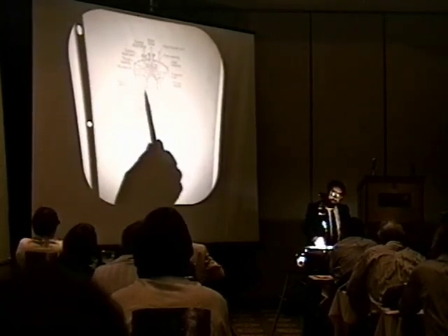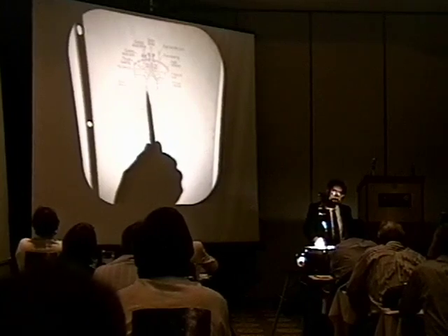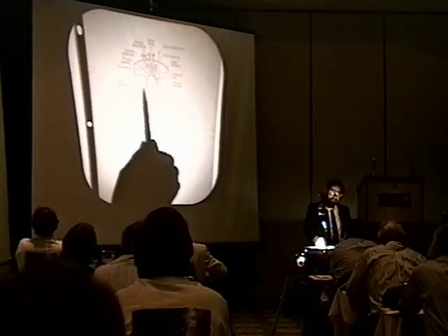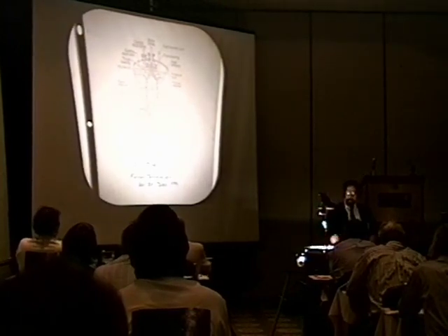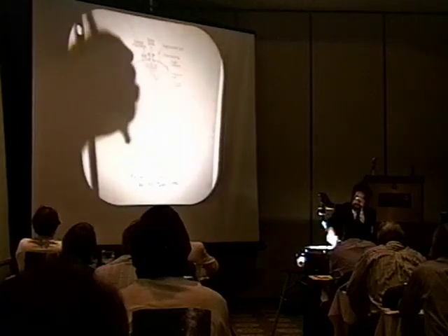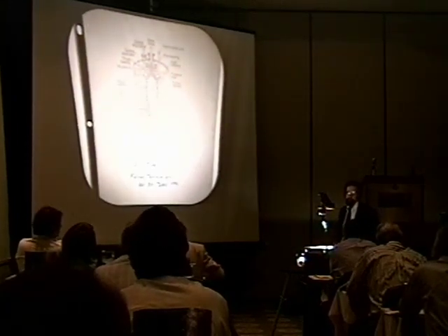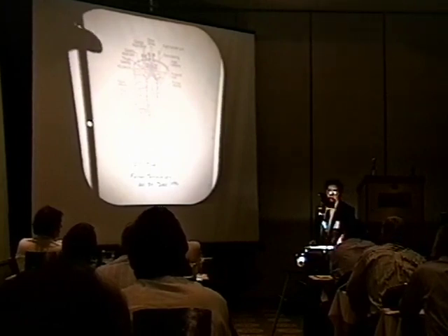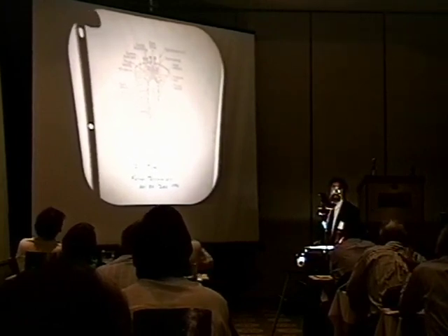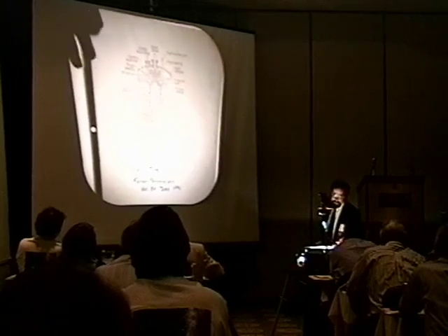It's basically a particle bed of uranium fuel with moderator, and it's spun up centrifugally, and then hydrogen gas is passed through this way, and then you get thrust. And the idea of particles is that you could get much better thermalization, much better heat transfer, and thereby have a higher specific impulse. Specific impulses for these colloidal core rockets are over 1,600 seconds.